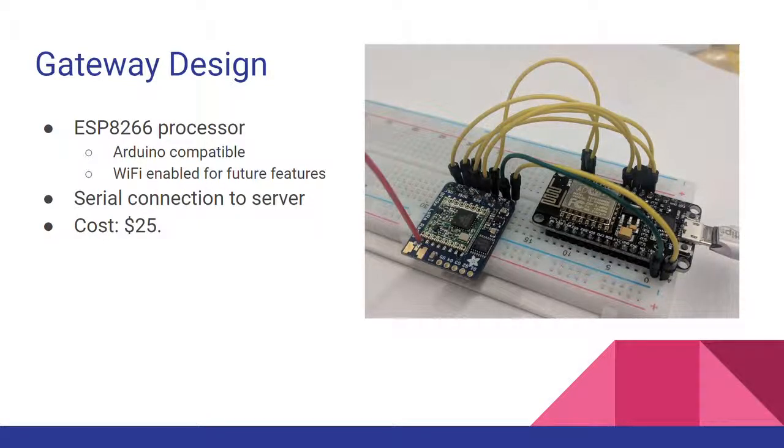There's an IRQ pin. It has interrupt capability so that the microcontroller doesn't constantly have to poll to see if there are new radio packets. This could be used for an interrupt-driven sleep routine, etc. So this is the design of the gateway.